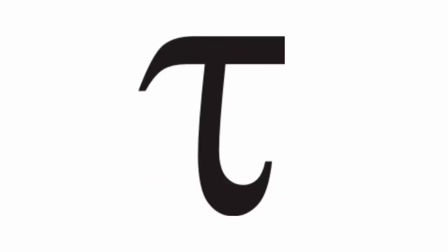We have just measured the time it takes for the capacitor to go from uncharged to halfway charged. We're going to call this T1/2. Your lab will explain how the time constant, represented by the Greek letter tau, relates to the time it takes to charge 1/2 the way. Your lab will also explain what the time constant should be in terms of the resistance and capacitance of your circuit.